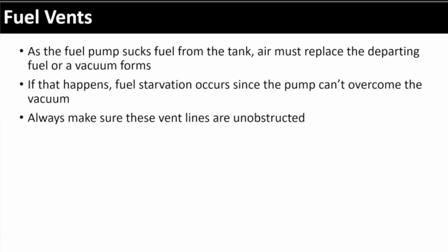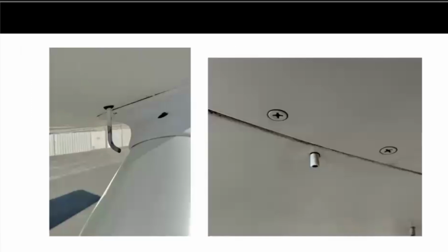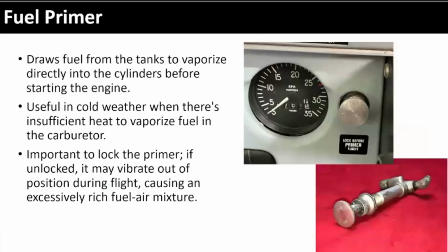Okay, so when you're doing your pre-flight, ladies, always make sure your drains and your vents are open and clear. Okay. Right, this is stuff we just talked about.